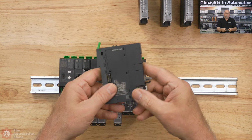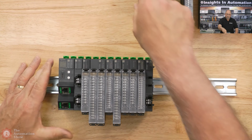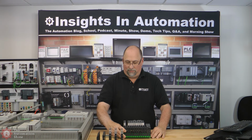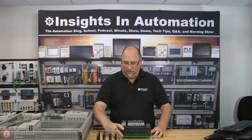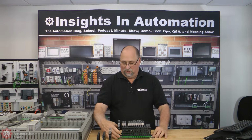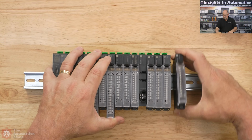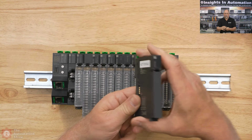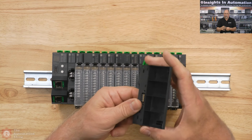I'm just going to put this other power supply module between the analog and the digital. So I didn't spend a lot of time engineering this order. I'm just putting them in an order I thought would make sense. And if you guys think I'm doing something wrong, let me know. But in any case, just putting everything together here. Okay. And I'm going to put the dummy module at the end and the terminator.